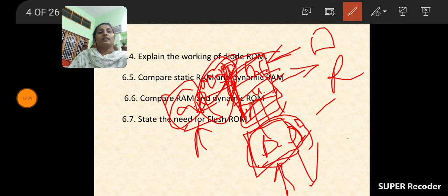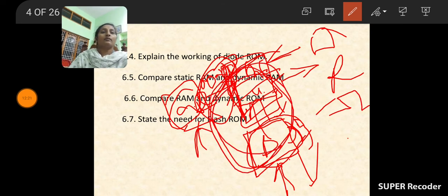Next important point is control lines. One is called write, the other is called read control line. If we are applying a clock pulse across the read bar signal, the operation going on inside is what? Retrieving the contents from the memory, that means fetching. If write is enabled, we are able to enter the data into the memory.